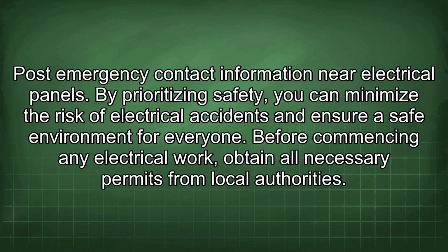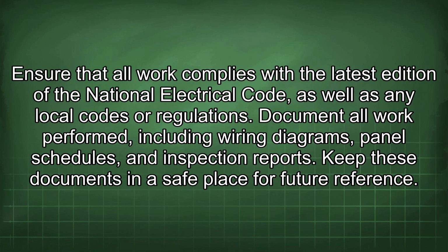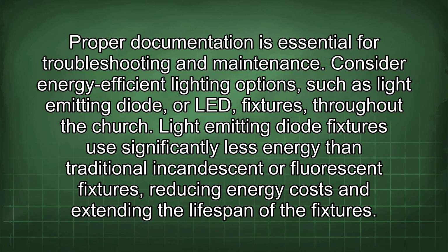Before commencing any electrical work, obtain all necessary permits from local authorities. Ensure that all work complies with the latest edition of the National Electrical Code, as well as any local codes or regulations. Document all work performed, including wiring diagrams, panel schedules, and inspection reports. Keep these documents in a safe place for future reference. Proper documentation is essential for troubleshooting and maintenance.